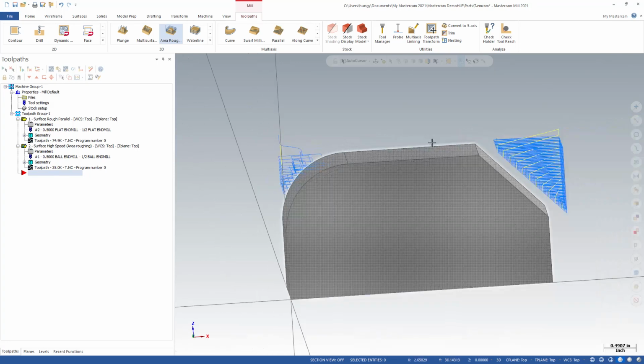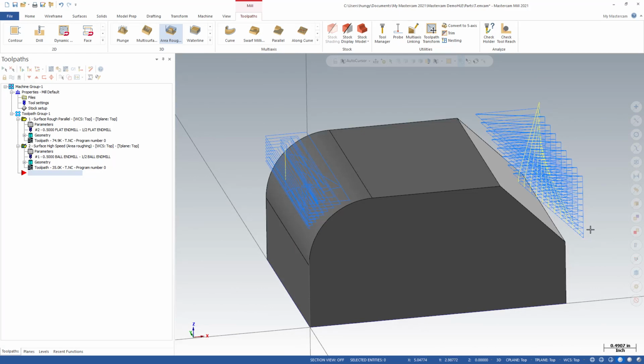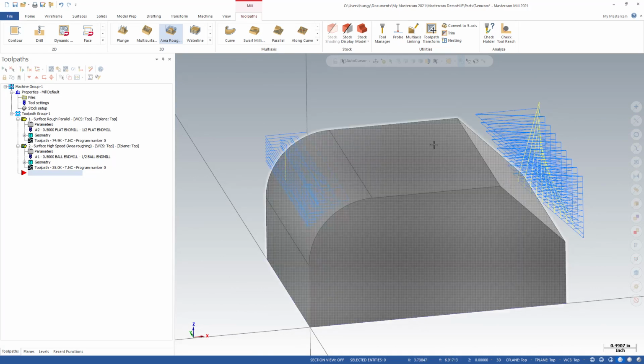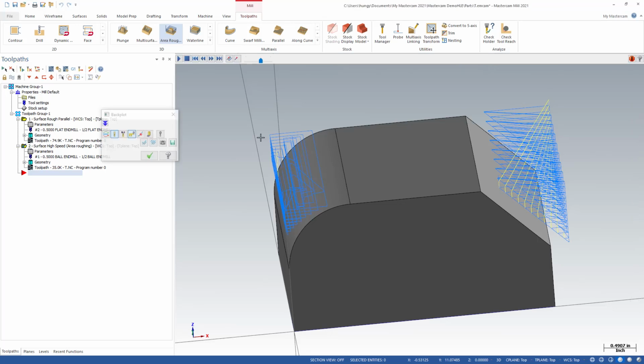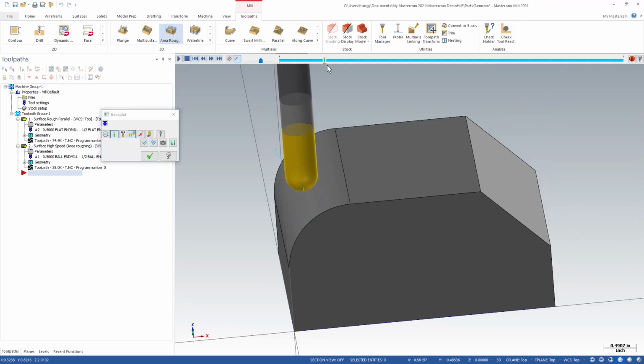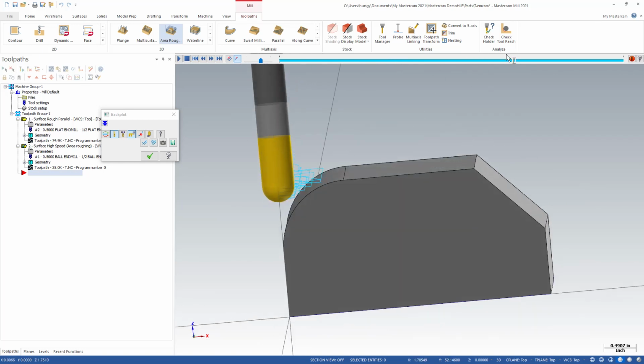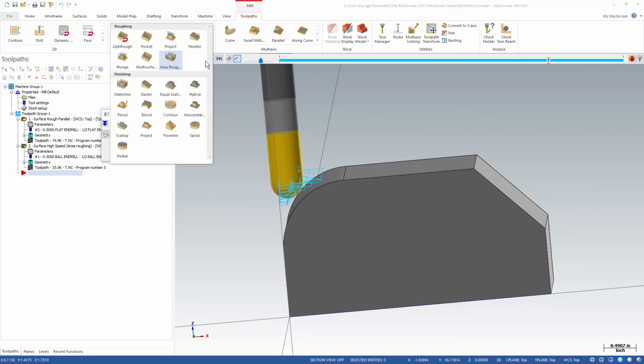area. Now the big difference between that is this one actually comes from outside, machines it in. This is actually from inside. If you can see the black plots. So you can machine it in and out. Typically, when you machine material, you want to start from outside, machine in. So both methods can do the same job. It's just that one can do much better than the other.